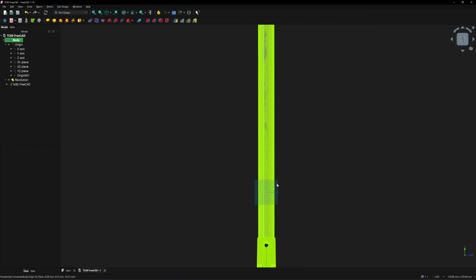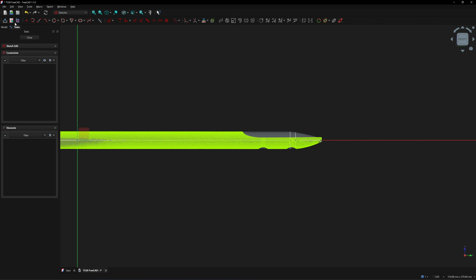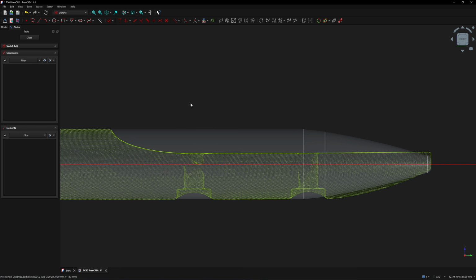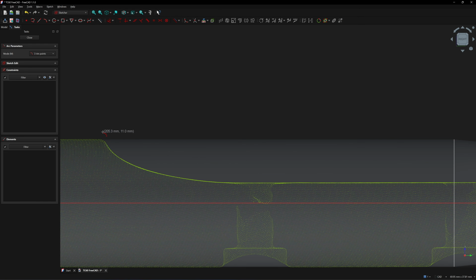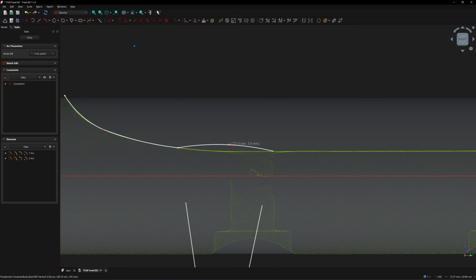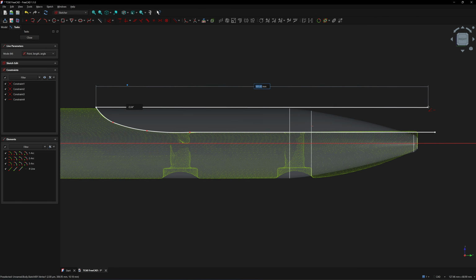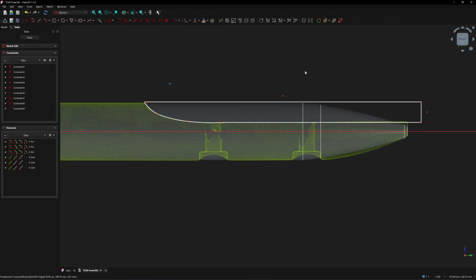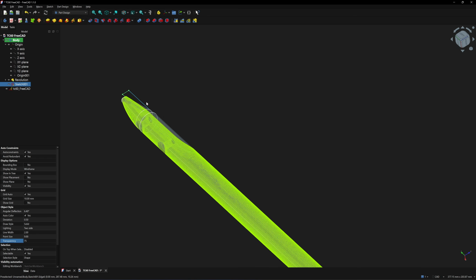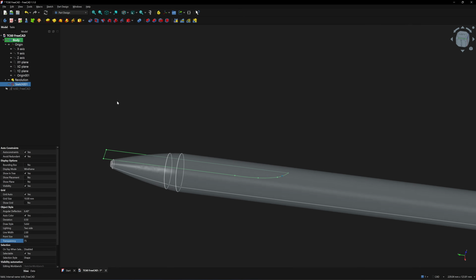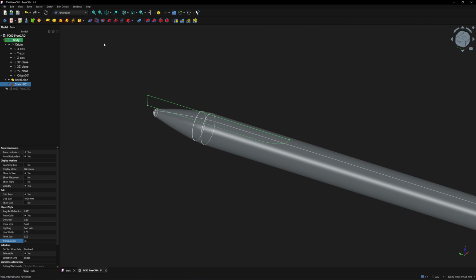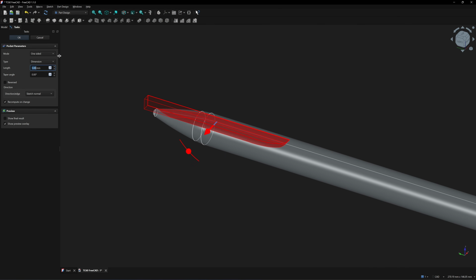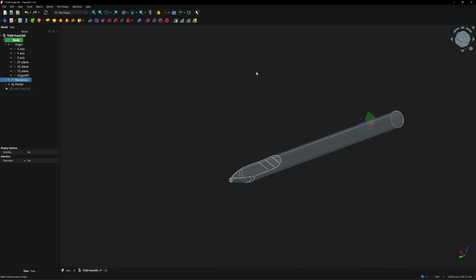Select the YZ plane, create a new sketch, turn on section view, and start tracing the cutting profile using lines and 3-point arcs. Make sure the sketch loop is fully closed. When all the nodes connect properly, they will turn orange. Close the sketch selected and run the pocket command. Switch to symmetrical mode. Then drag the arrow until the entire area is covered.